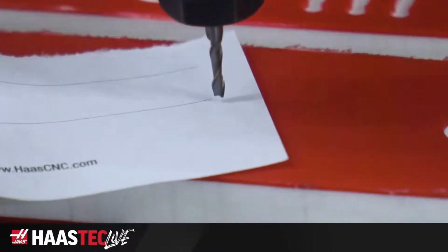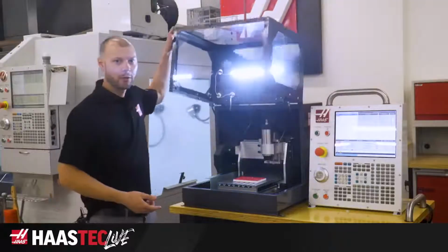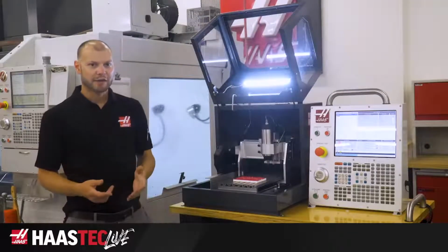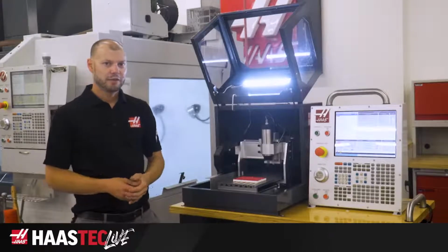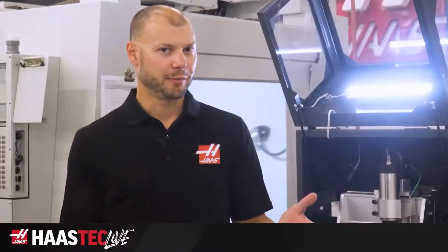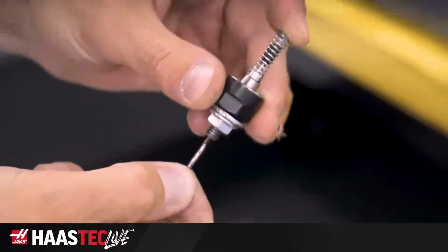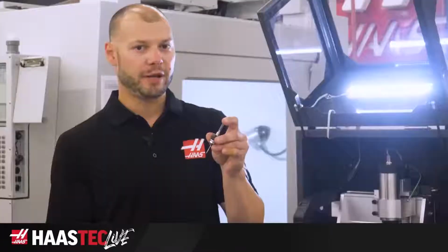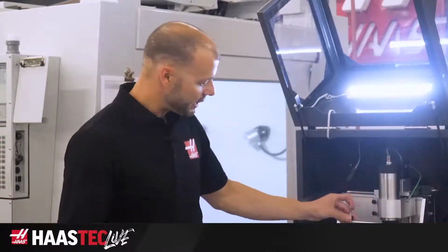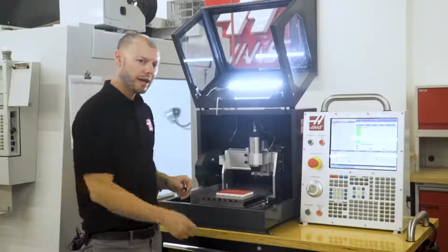I want to show you how easy it is to set up the desktop mill and use VPS conversational programming to generate some code. So you can see here I have a couple blocks of plastic on the table to work with. We mostly recommend cutting plastic or machinable wax on this machine since the material is cheap and reduces damage if a crash occurs. Or, for the ultimate in simplicity, we offer the spring-loaded pen attachment, which mounts directly in the spindle. Then, you can put a clipboard and a piece of paper on the table and use the desktop mill to draw shapes with CNC code. But today, we're going to make some chips.